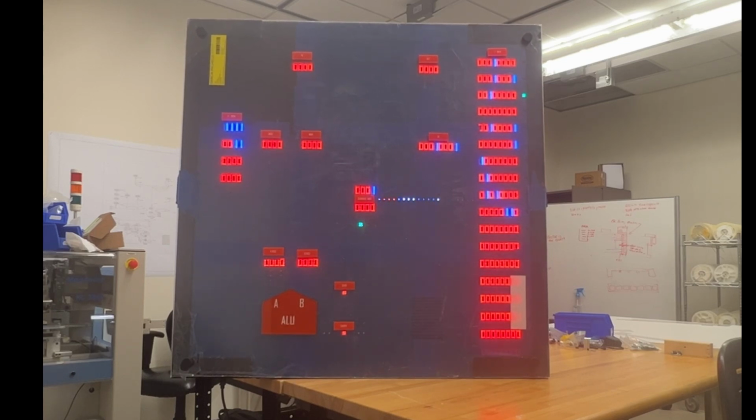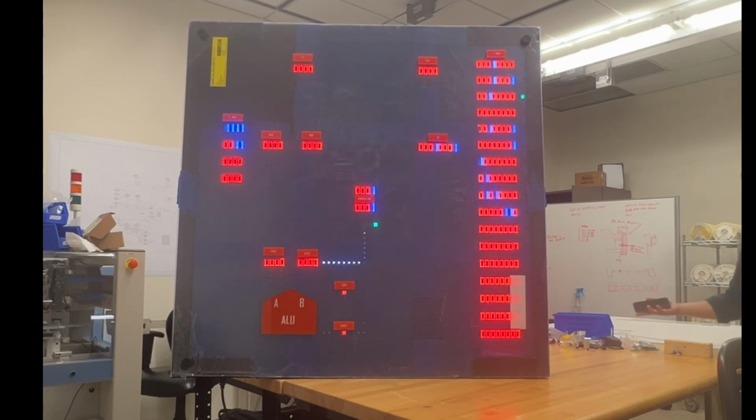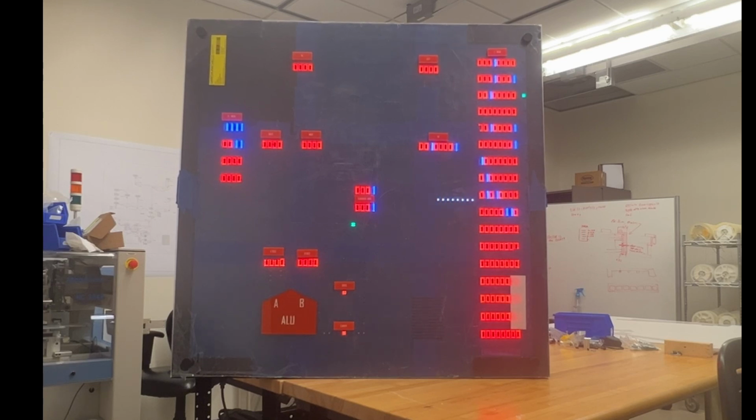After the values have been written to both registers, the program then decides to perform an add operation on both values. The 2 values are added together, the ALU flags are updated, and then the exported result is held in the A register. Afterwards, the A register's value is then outputted to the out port in order for an observer to be able to view. The program then runs a jump command, which allows the add and output instructions to be looped for an indefinite amount of time.